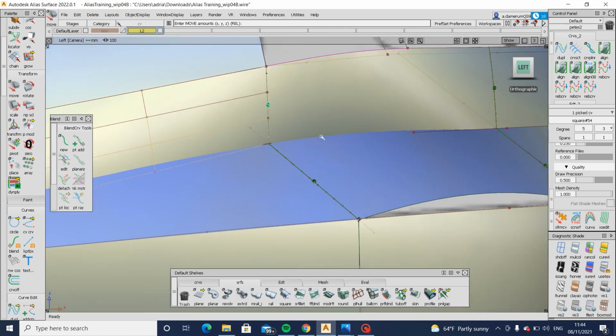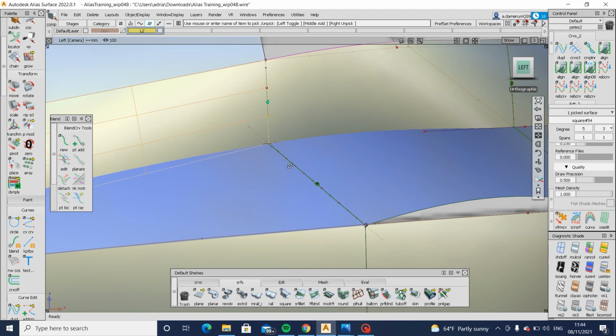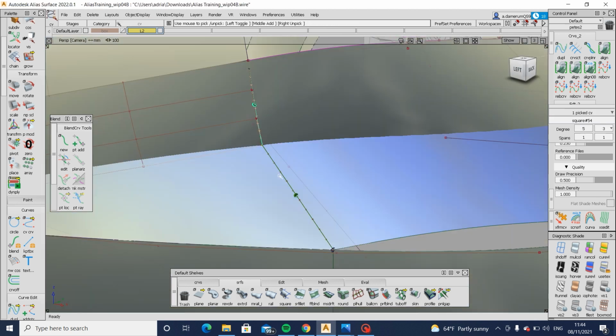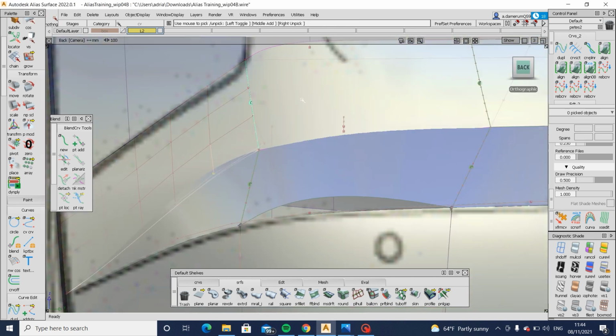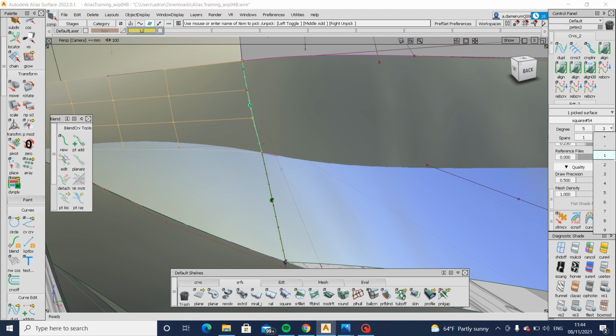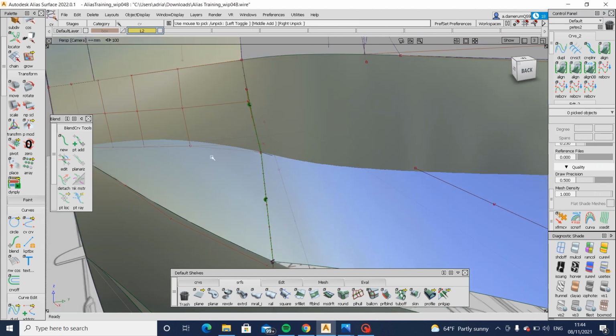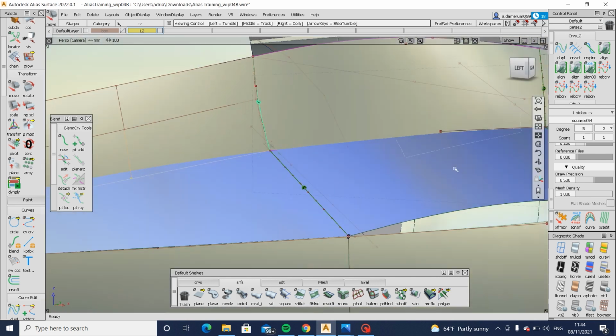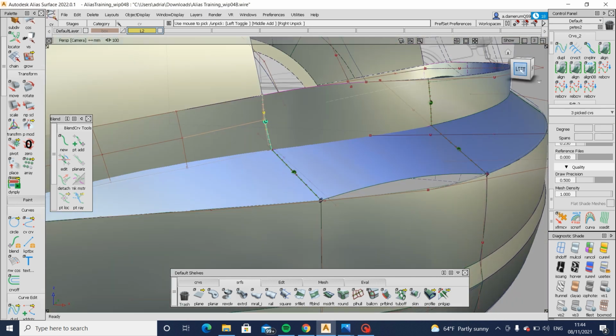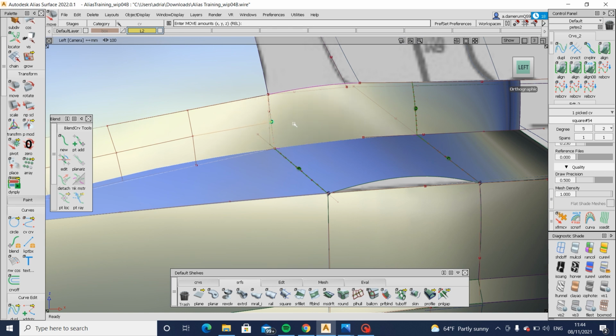Basically, I'm trying to get it so this intersect runs better, and yeah, so I was right before where this point needs to come down. So that's what I'm going to do. Just, yeah, got confused. Bring this down. Probably be easier if I reduce the number of CVs on this surface again. Bring it down to 2. More control. Let's get rid of that curve. It's getting in the way. That's better.